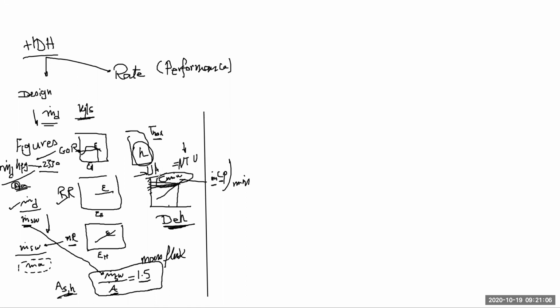Yes, it basically gives the same number, but normally the value of the overall heat transfer coefficient is given to you because calculating it is a little bit involved. You have to go for forced convection inside the tubes and a kind of condensation on the outside surface of the tube. So the correlations would be a lengthy process, which is not the target. The target is how to calculate the surface area. That's something you can probably ask in a project, to calculate the details of the overall heat transfer coefficient. Did I answer your question, Salah? Yes, Muhammad.